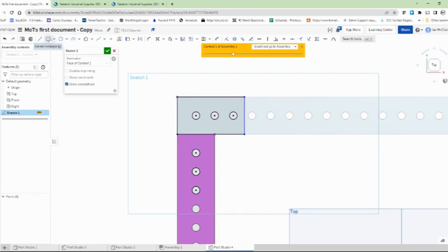I'm going to do another rectangle. And same thing, now I've got a point to refer to, so I'm going to click that point, going to go over and then down. So I haven't clicked yet, and there we go. So what I've got here is I've got two rectangles, and I want to eliminate that blue. The letter D on your keyboard opens the dimension tool. So I can select the line, select the point. So click on the line, click on the point, move your mouse, and we'll put that quarter of an inch, 0.25 inches away. And 0.25. Okay, so now I have a rectangle that's perfectly constrained.